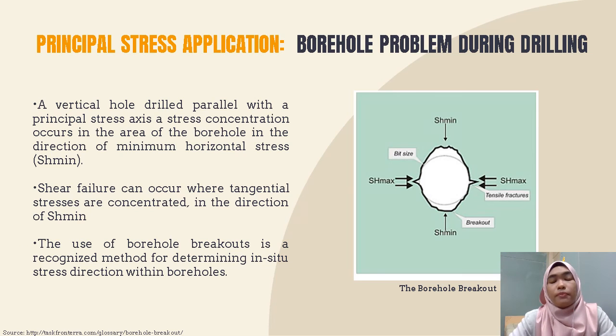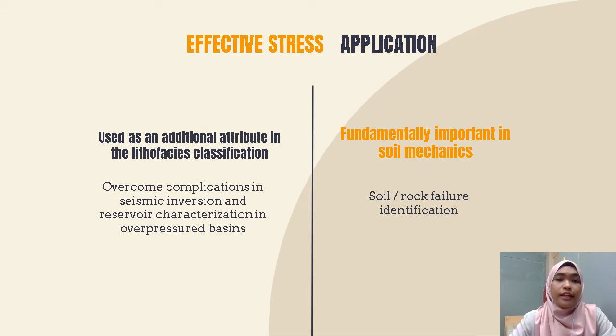So one of the applications of the principal stress is the borehole problem during drilling. It is used for borehole breakout as a regularization method to determine the in-situ stress direction within the borehole. It is to ensure the wellbore stability and to avoid collapse of the hole and also to keep the pore pressure of the formation. So next, the effective stress applications could be used as an additional attribute in the later